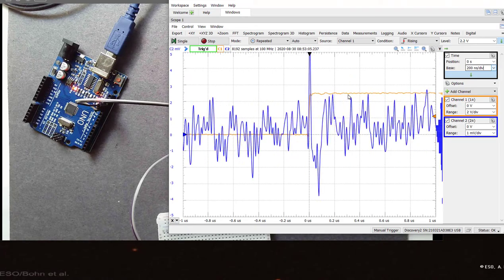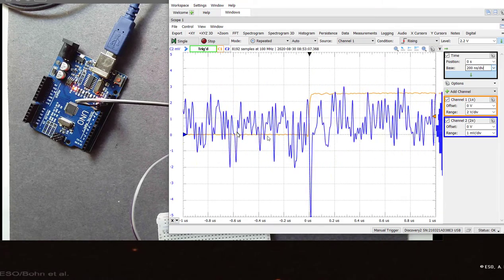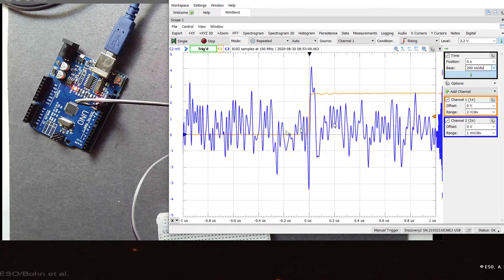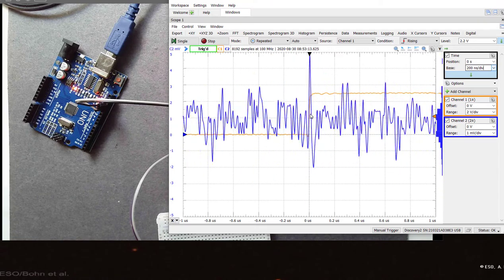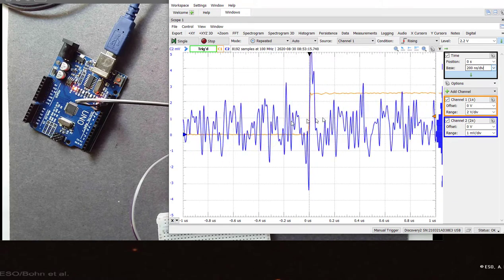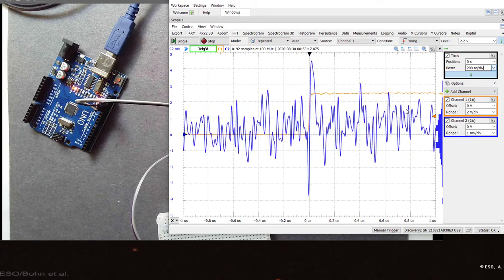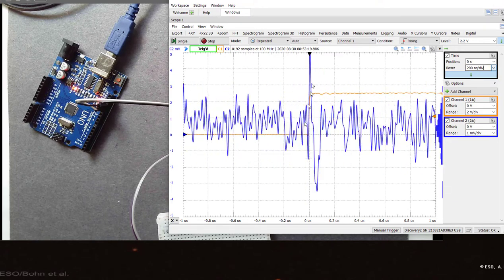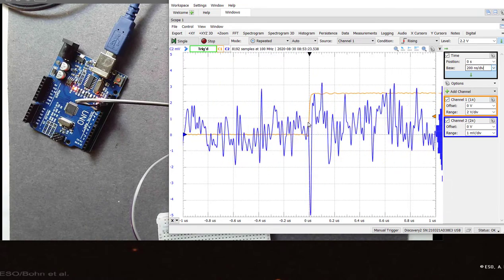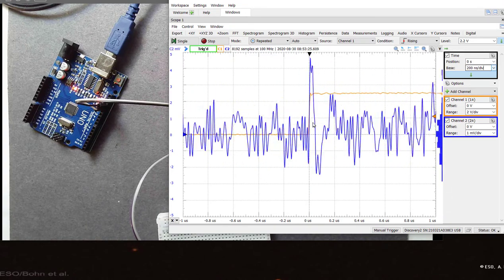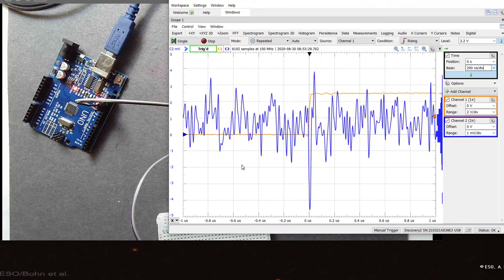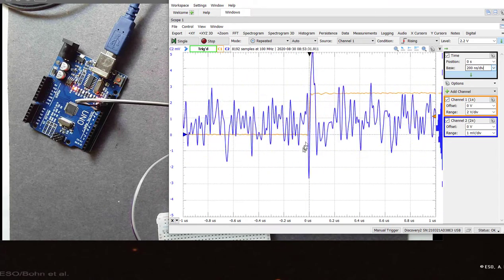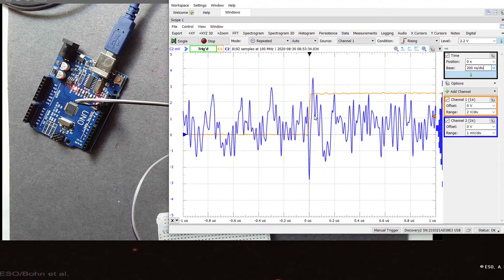And so here's the trick we're going to do. Most of this noise is random. If we average this buffer and take the next one and the next one, we're always triggering on channel 1. All the random noise is going to average away with the square root of the number of averages. Any real signal on channel 2 that's always there will stay there, but we'll average out all the random noise and drop that. And so the noise level will drop, the signal level will stay at the same level.